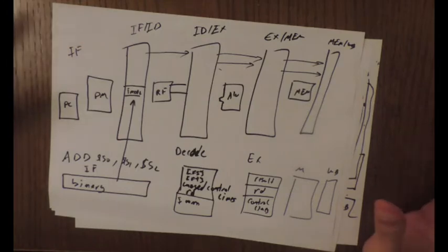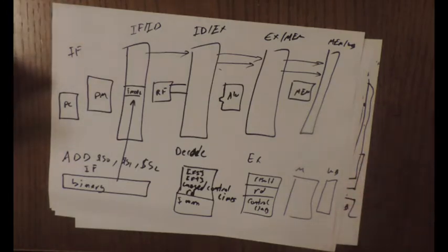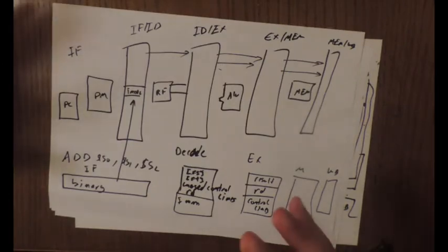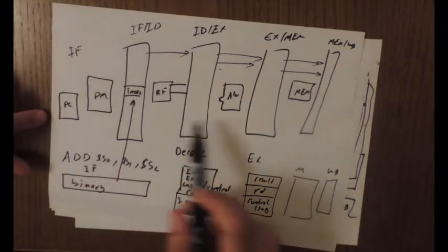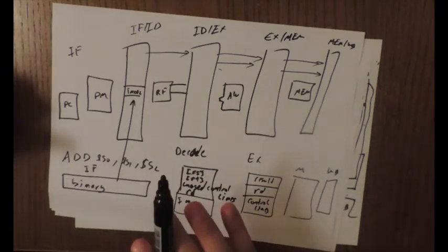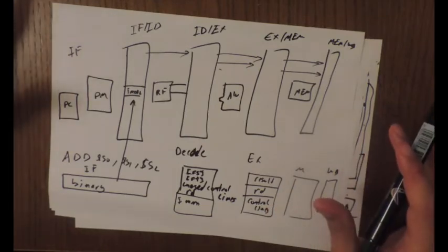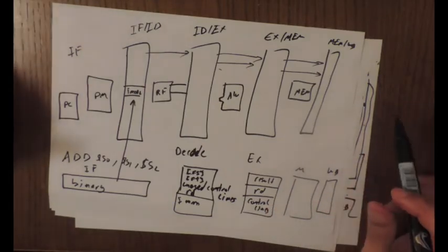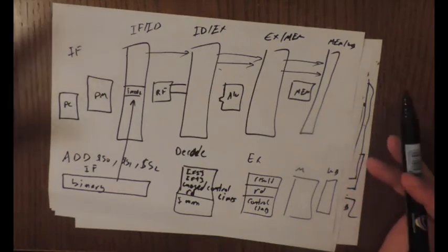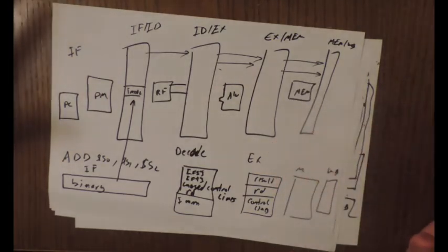So this is how the hardware of the pipelining works. So this is what we mean by having 5 stages. It's all controlled by a clock. Each instruction works in a pipeline. We have a maximum of 5 instructions at the pipeline, and we cannot have more. If you want to have more instructions at the pipeline, then we need to increase the number of pipeline stages.